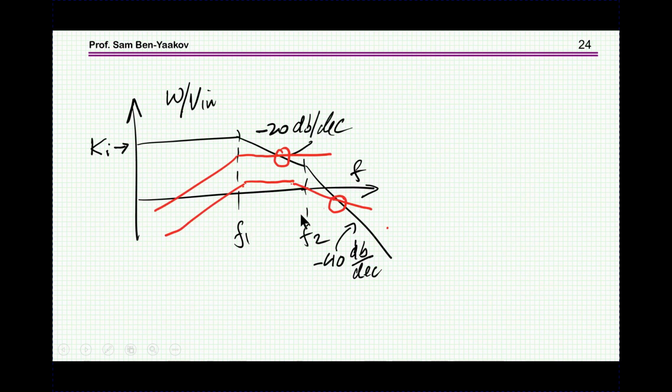And here we see that we can do it two ways. We can do it with a 1 over compensator, 1 over B as I called it earlier, that looks like that. Or I can have one which looks like that. This is now 20 dB per decade going up the 1 over, while this goes down by minus 40, so the rate of closure is 20 dB, and same thing for here.